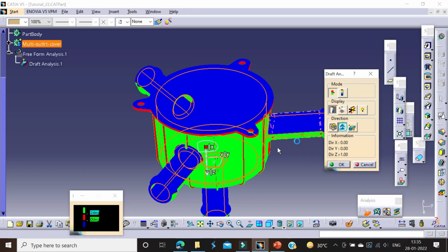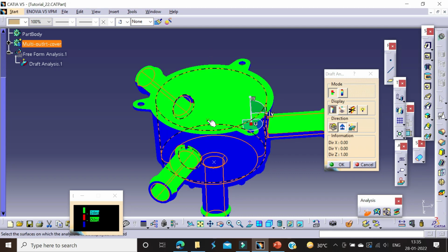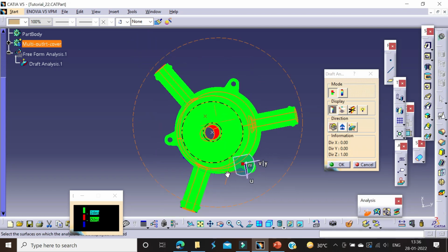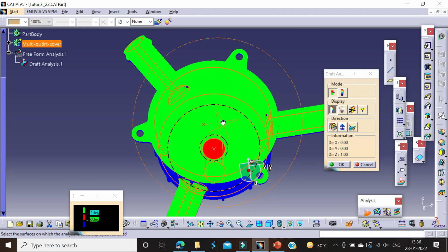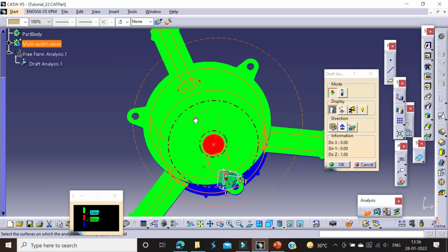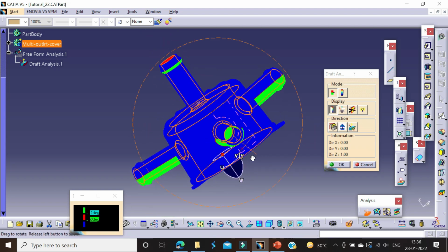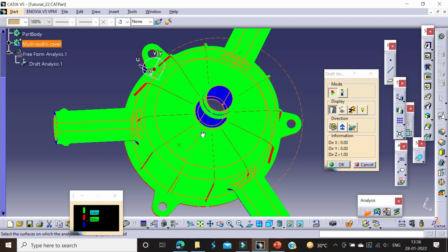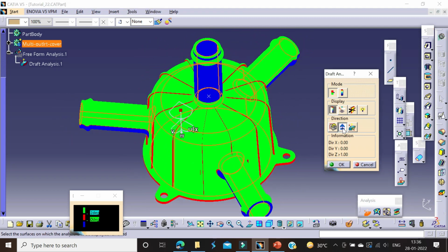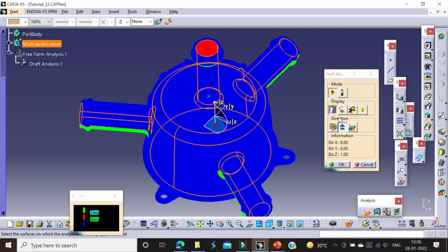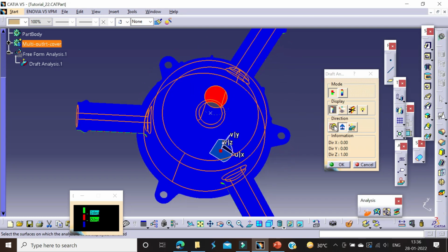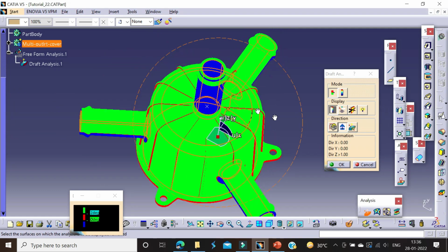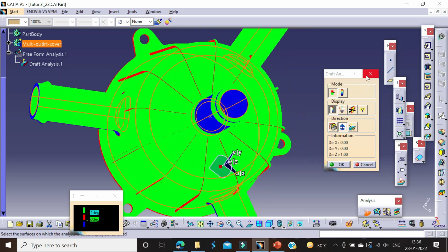This is the component having the multi outlets, and it is under the category of a complex component. So the tool also has complexity, and for that, sliders and lifters are going to be used. We can see the portion having the Z direction as the tooling direction. So for some outlets, sliders and lifters are required.